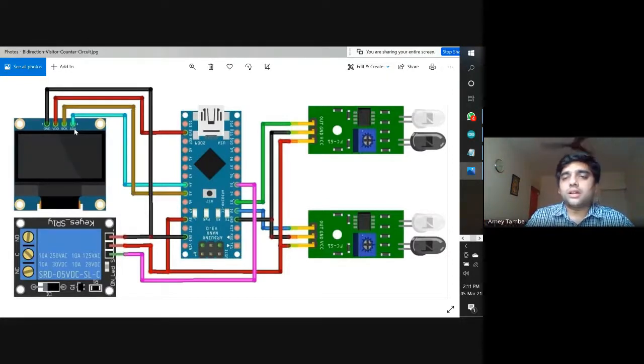And when you have 5 or 6 pins on the connector of a display, then it is an SPI display. We'll take SPI and I2C in our protocol session, where I'll explain why there is a difference. The pretty straightforward difference is the chipset these devices are using.